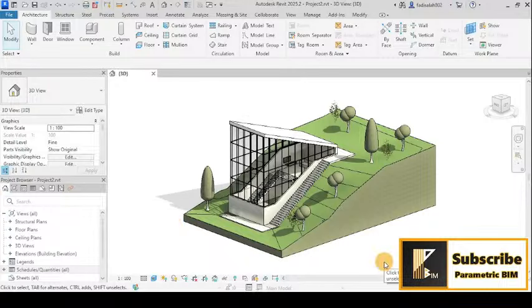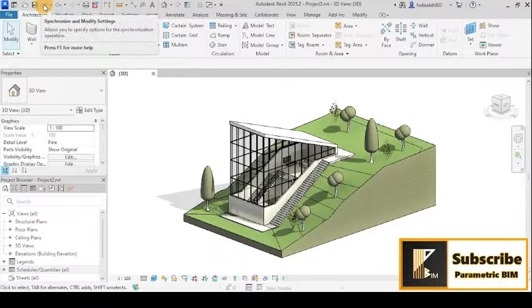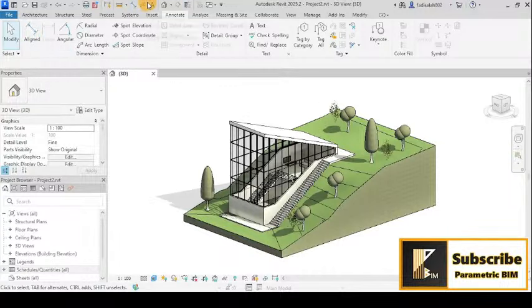Now we will talk about the quick access bar. As you see here in the upper side of Revit, you can see some symbols. This is the quick access bar, as we call it, and as you see we can save, we can open, we can synchronize or print or do anything, and it's called quick access because we can go directly to the command here without going to any ribbon. So this is the quick access.